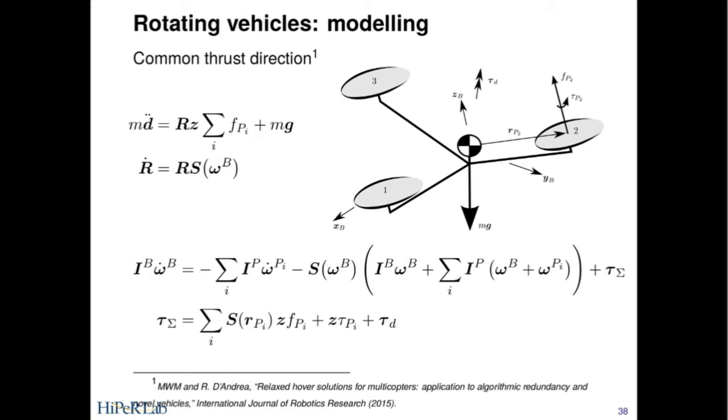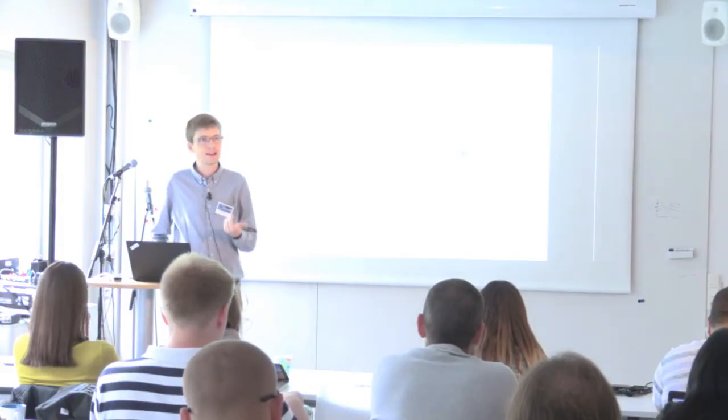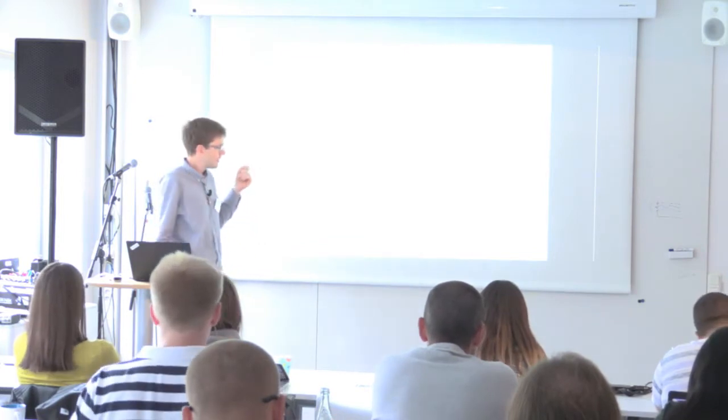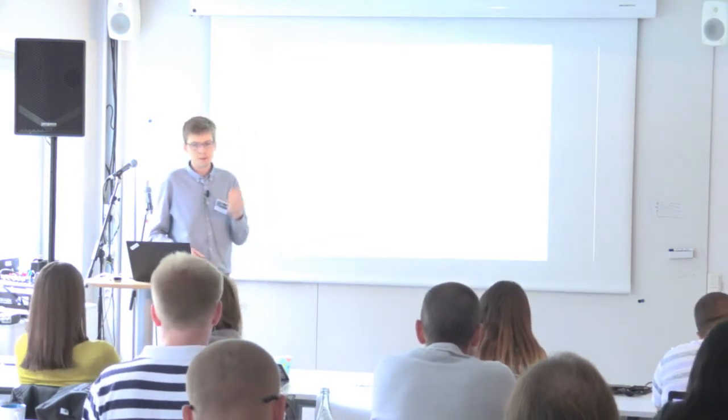And what we did yesterday is we talked about how do I create a vehicle to, say, survive disturbances when doing inspection. And we saw that the way to analyze this was to try and linearize the system around its equilibrium conditions. So we try to describe where we want the system to be, and then we talk about small perturbations from this equilibrium. So small differences from this desired position, and then we can analyze what happens to these small disturbances. So in this case, it is slightly more complicated to talk about what an equilibrium is.